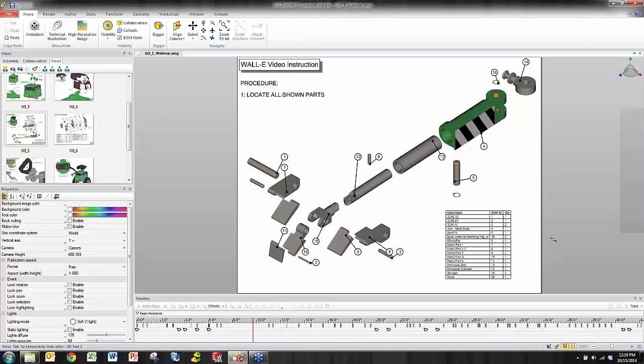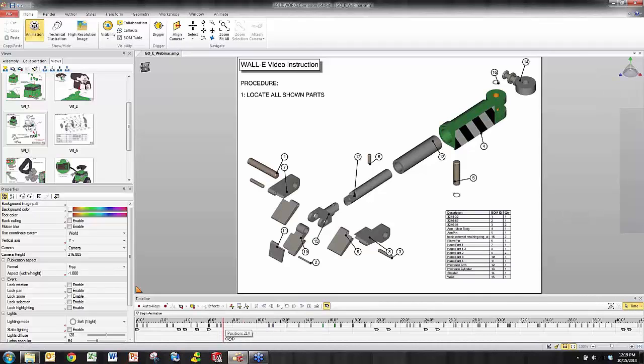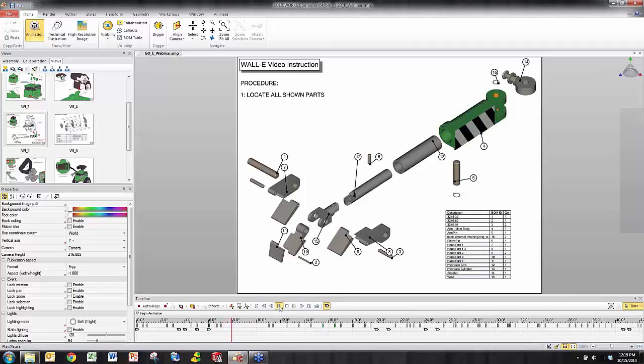Very cool. So let's walk through this animation now. There may be some portions in my animation where I want the animation to actually stop. I think right here is a good portion. If I'm going to publish my animation in AVI format, a user can just hit pause. But if we want to include this in an interactive document, I need to give them a place to pause, or maybe I pause it for them so they can see what's on the screen.